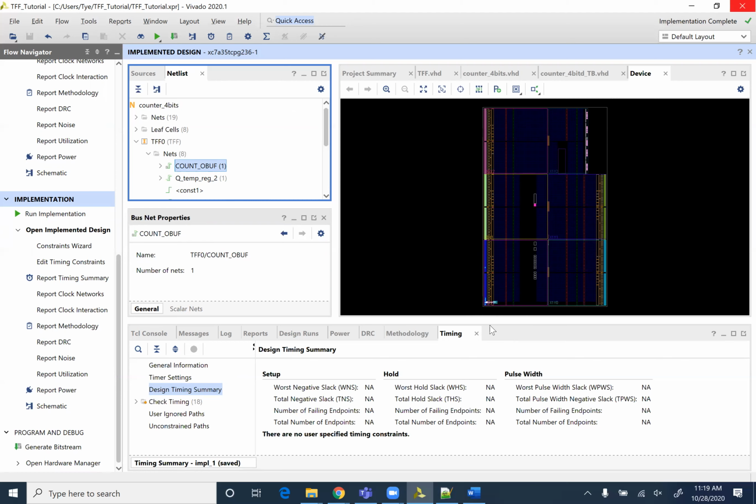The FPGAs have what we call built-in multipliers. If you say, I want to multiply A by B, it will go to the multiplying cores and use one of those, and you can see how many of those you have left. There are finite amounts of resources, and this can help you allocate them. If you've made something too big, you may need to start thinking about logic simplification or buying a bigger FPGA.